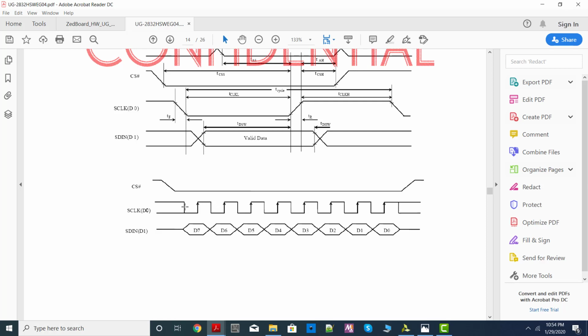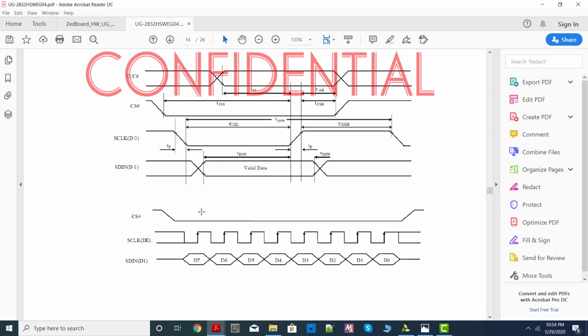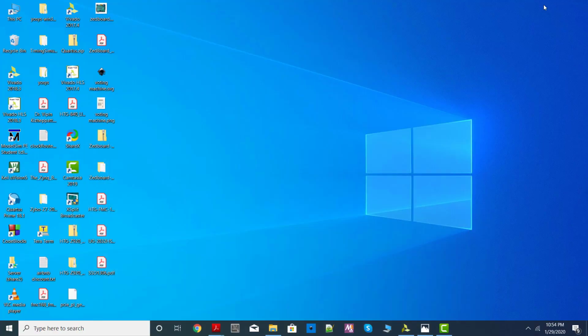So this is what we are going to do. Whenever we need data communication, we will have clock, and whenever we don't want to communicate, we won't have a clock. Instead, we will have a high signal on the clock pin. Fine, so today we are going to design only this SPI part, and the remainder circuit we will design after testing our SPI. Okay, so basically today we are going to design an SPI controller.